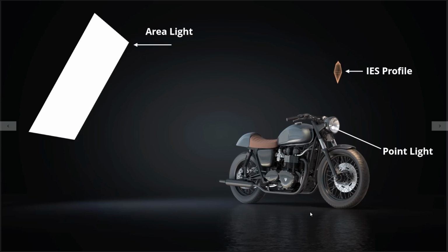And then on the inside of that assembly is a point light. And that point light is casting. You can see the light that's visible on the tire there. So we've got 3 different physical lights in the scene, and they've each got a specific job. There's also, and you can't see it, but because this is rendered on a backplate instead of the environment being visible, there's still environment lighting in this one. We used an image pin on this one just to give some more interesting reflections there.